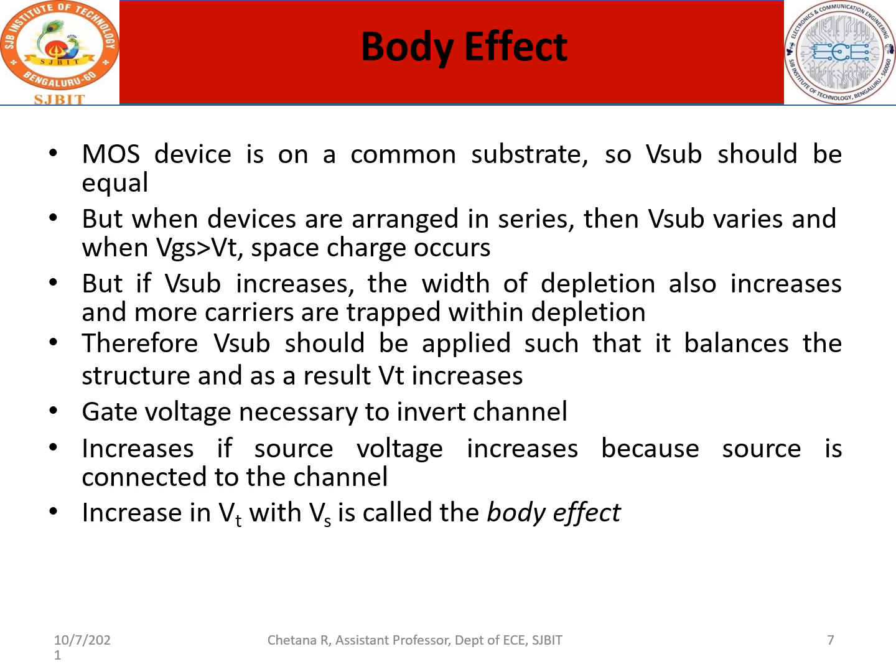Yes, very much true. An increase of the source voltage increases the threshold, because the source is connected to the channel. Therefore, the increase in Vt with Vs is called the body effect. Ultimately, please try to understand that if there is any variation in the substrate voltage, many effects are seen. Those effects are very abrupt, so the depletion region of the channel will vary, the same amount of carriers are trapped, and you can only see a saturation current. There is no proper current flow. You should see current flow in three different regions: cutoff, linear and saturation. You will not be able to see that.